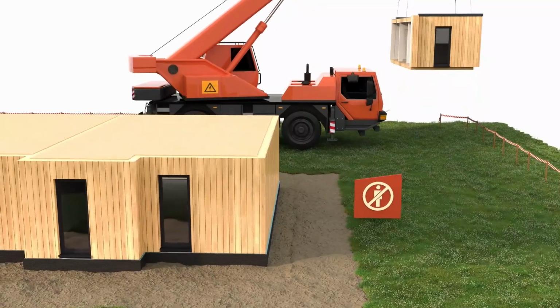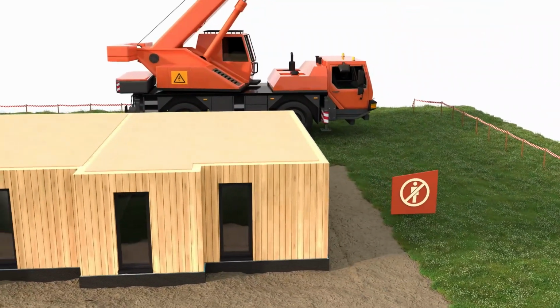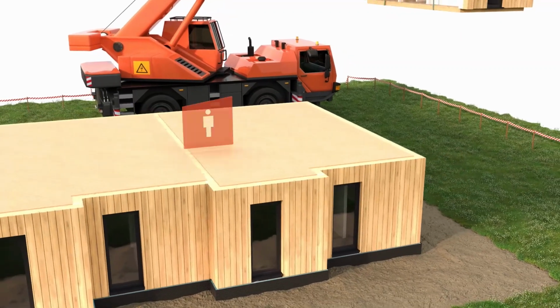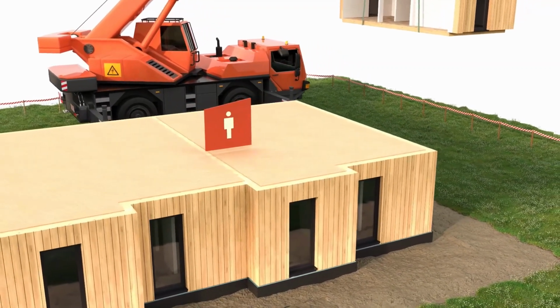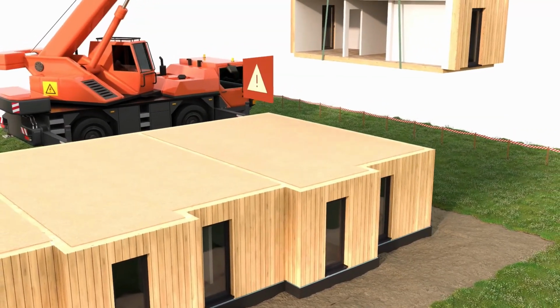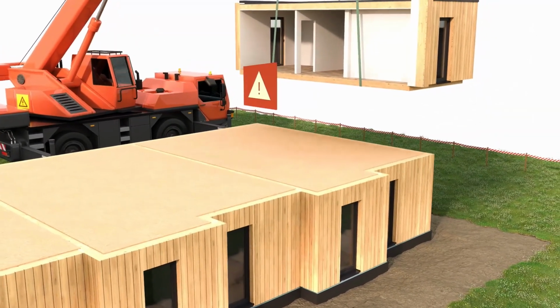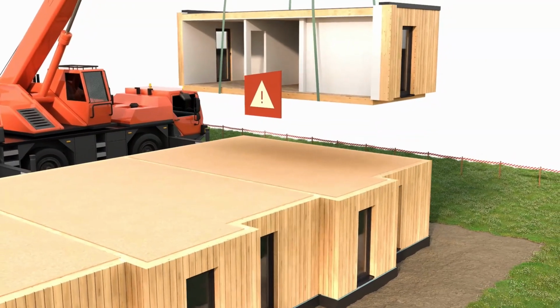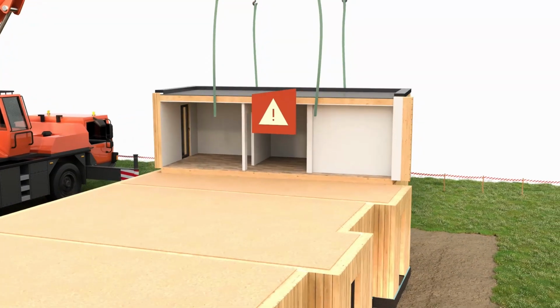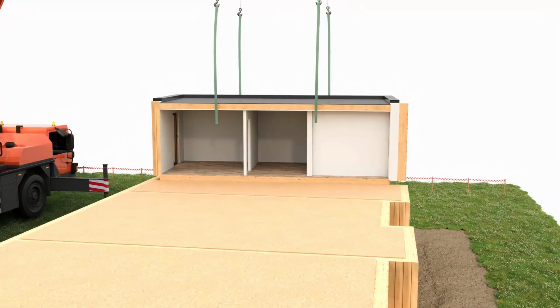Working under a lifted load is strictly prohibited, and the lifting zone must always be segregated. Only those who are actively working in the lifting zone are allowed to be present. It's also important to be aware of hazards that are mostly hard to foresee, such as the breaking of a crane's cable, which has actually happened and occurs rarely, but is all the more unexpected when it does.